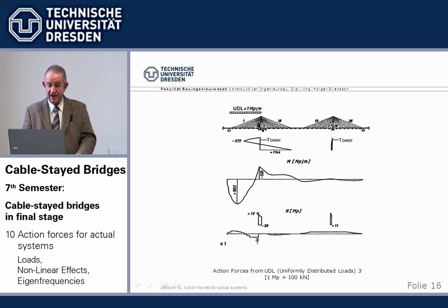If we load the side span, on the other hand, then we have here the big positive moment, sagging of the beam, and there's nothing here, so it's negative here, and then it tapers out.